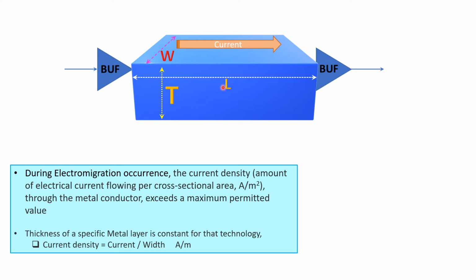In an SOC design you can have the same metal 4 conductor drawn with different dimensions. In general in SOC design you will draw with single width, double width or triple width. But in analog design, generally you will draw the same metal 4 with multiple widths. It doesn't need to stick to a specific integer multiple of widths.